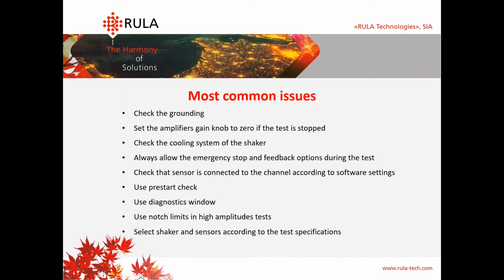First, what would happen if a sensor cable is broken during the test? If the sensor cable is broken, I think the voltage to acceleration value, which is being checked during all the tests, will work, and you'll get an emergency stop. I get such results during some kind of tests, and in that case, the test will stop automatically. So an emergency stop or a warning? You'll get an emergency stop. An emergency stop, okay.